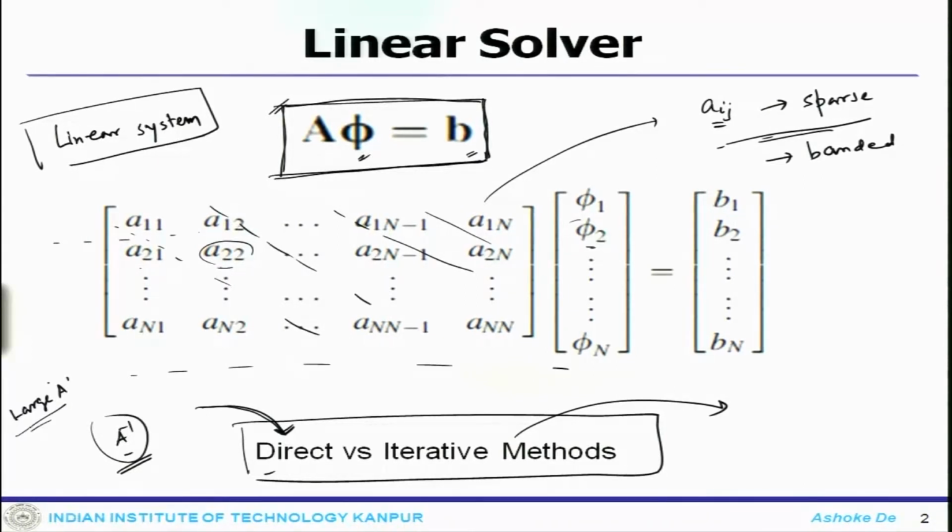So, that is essentially for a large system one can think about it's impractical. And when you talk about the physical problem, this matrix is going to be some sort of a n by n, and this n is the number of total cells count in your 2-dimensional domain, and when it goes to 3-dimensional you can think about the size.